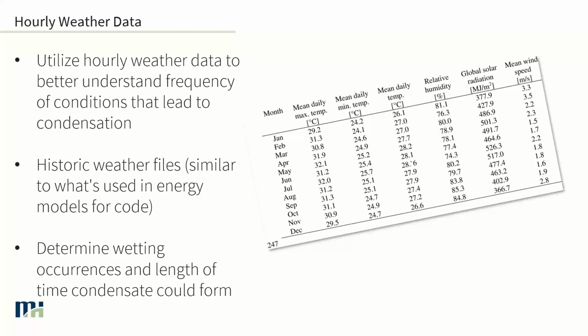So we could take that. It contains your exterior temperatures, when you have bright sunny days, which may lessen or increase the temperatures on the glass so that you don't have those worries about condensation. It has wind speeds on the outside. It's got clear night skies if you're worried about night sky radiation cooling down surfaces. It's got exterior humidities. So there's a lot of information that we can use to then further assess what the risks are. So we can find out, if there is a risk of condensation, how long does it last?